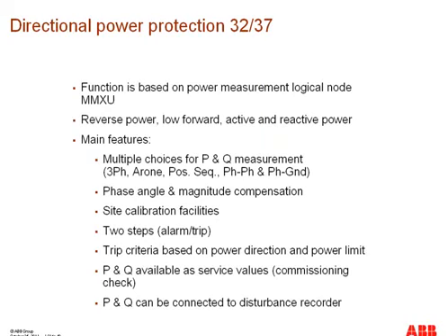Multiple choices are available. It can be three-phase, Aron, positive sequence, phase-to-phase or phase-to-ground quantities, and these quantities are used for this directional power protection.